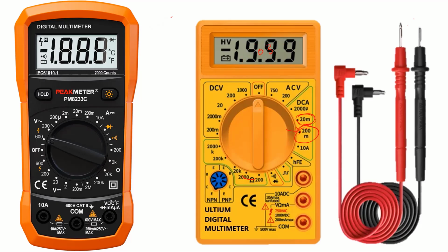So each time you turn to the zone, remark how the digits are written there, and the digits written there will be in the orders of 00 first when you have not connected anything. So switch it and see when there are zeros and observe the pattern. So that gives you exactly the precision of the instrument or of that particular zone, so that when you're writing down your values, they should respect the precision of the meter. I hope that's clear. So that is how you use a multimeter.